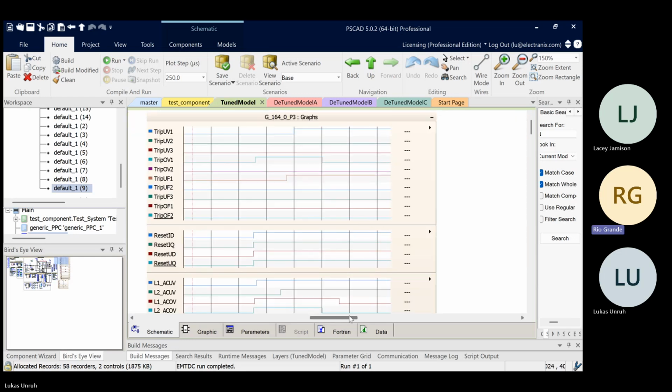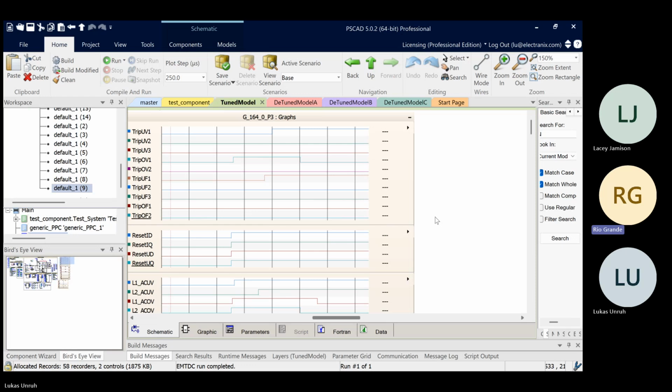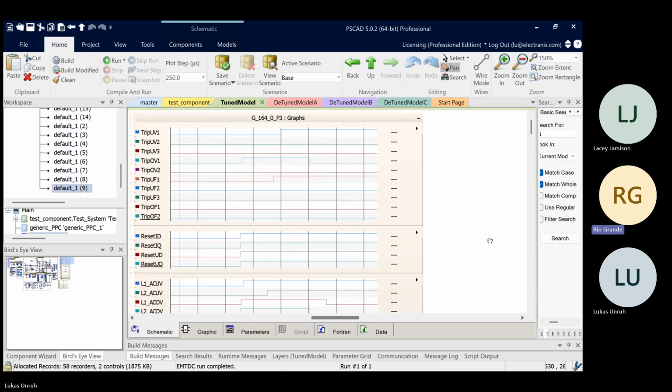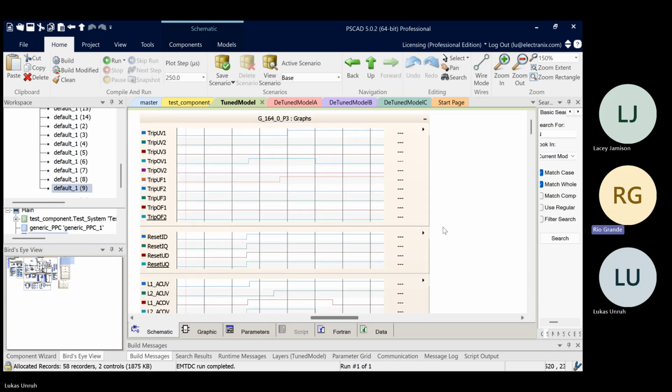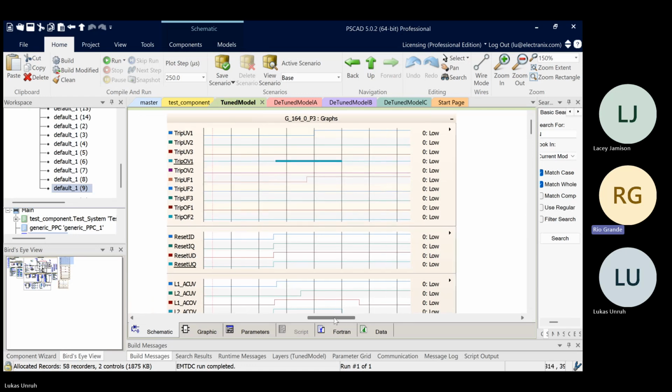But there's a lot of models that have two things usually that they'll tell you. They'll tell you if they're in a ride-through mode, like if their LVRT mechanism is active at that time. Or they'll often tell you, if they trip, which element tripped, or what sort of error code was thrown by the inverter. In this case, there's a few things that come up, but the one that comes up first here is over voltage 1 setting.